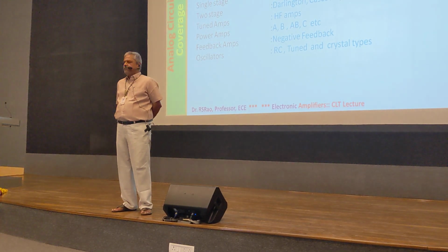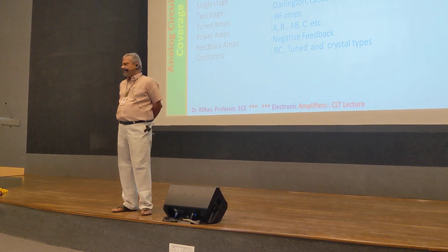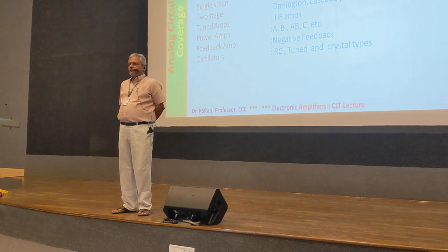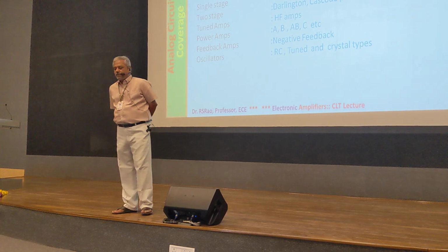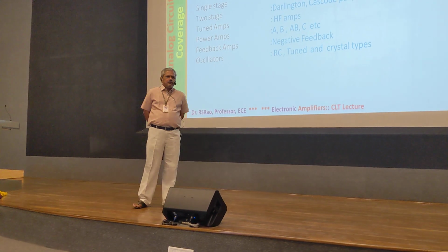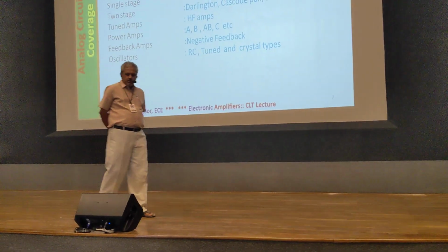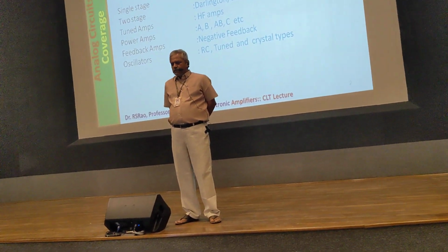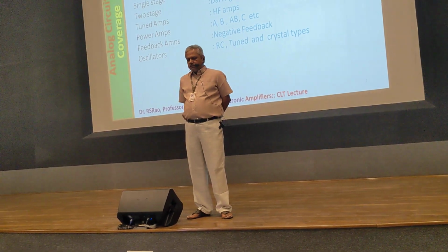Two things they do: filtering plus amplification. To provide filtering, to give that functionality to the amplifier circuit, tuned circuits are used as a load.